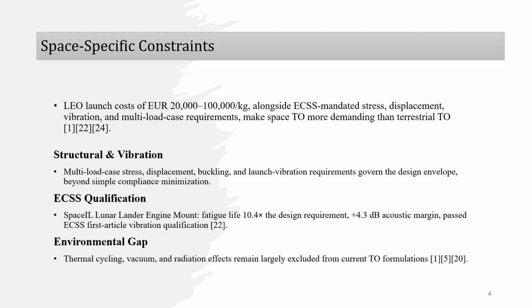In space applications, the optimization problem is constrained by much more than compliance and volume. Launch vibration, acoustic loading, stress limits, displacement requirements, fatigue life, and buckling can all govern the final design.